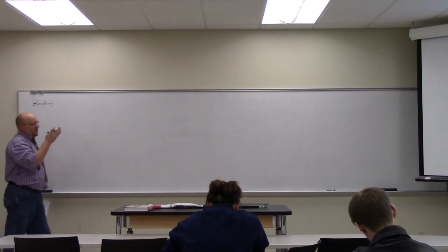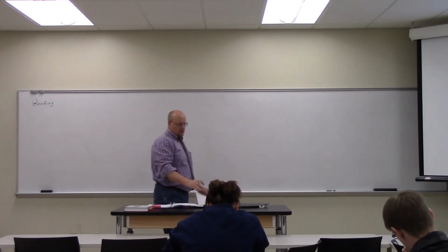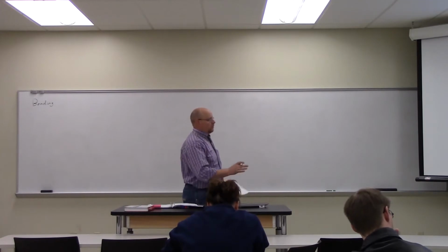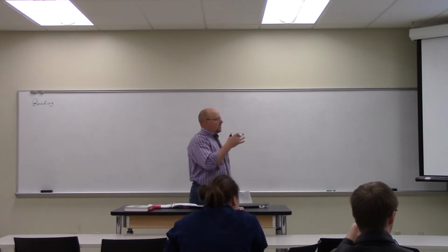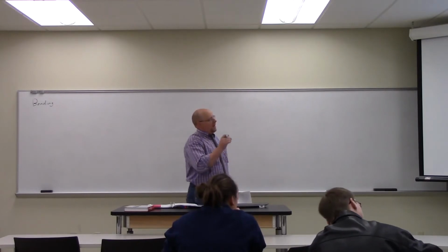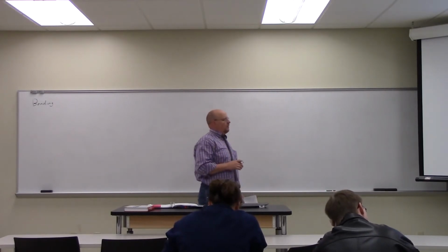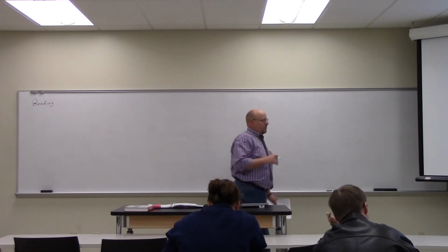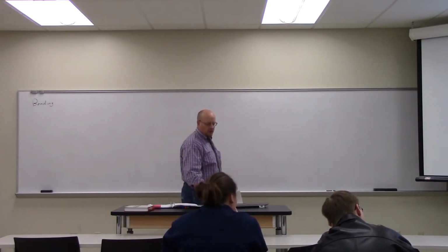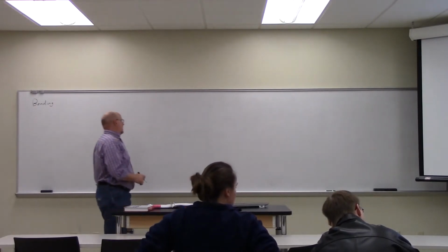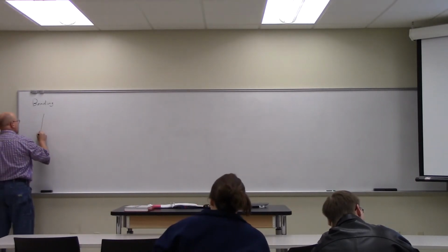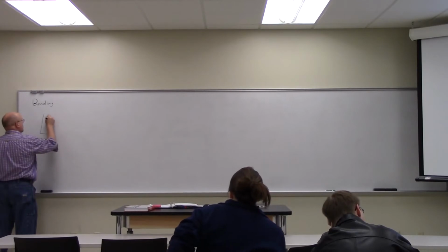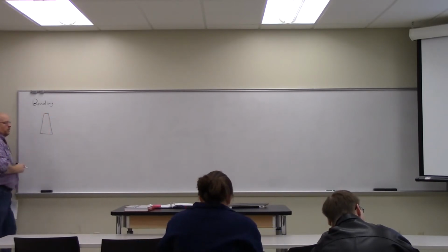So if I take a slice out of this thing, so here's the second figure. There's sort of the macro view, right, of this thing being bent, and I'm going to take a slice out of the center of it. You can see the slice delineated there, the delta x slice. If I take the delta x slice, while it's being bent, that slice becomes a trapezoid.